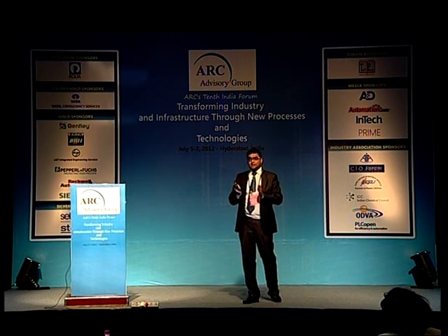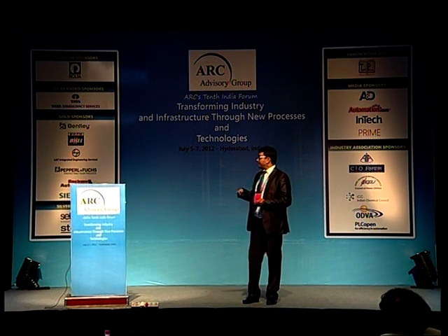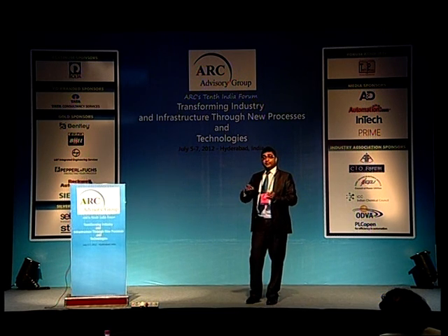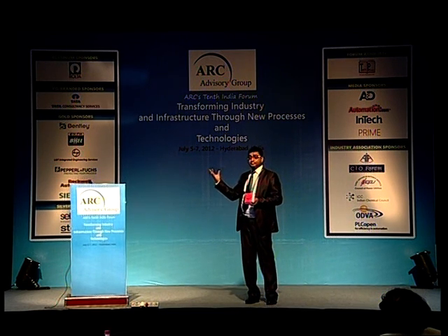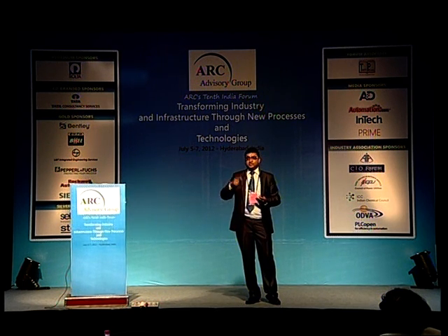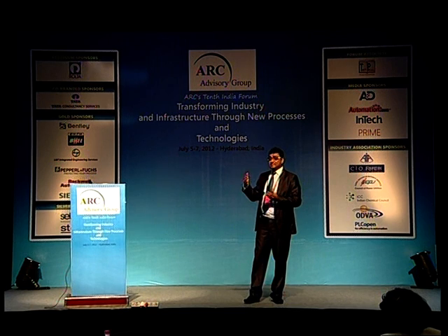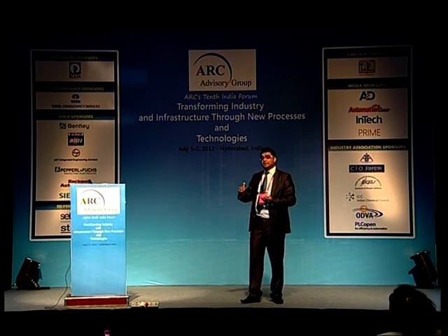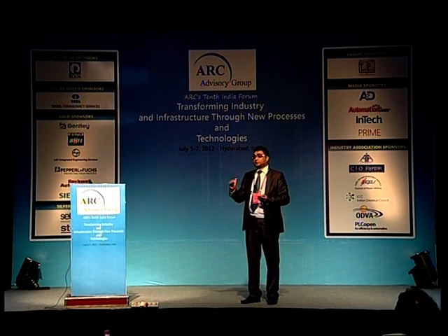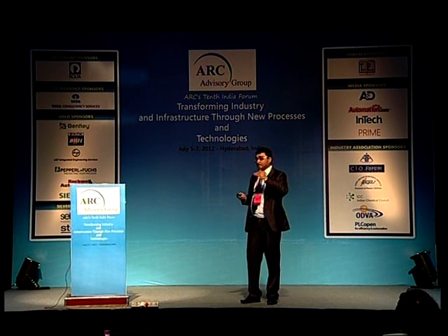That means especially for rotary equipment like fans and pumps, where there are vibrations or winding temperatures. For these particular systems, a lot of measurements are coming in as input data. So if you take the trend of this measurement data, it is very difficult to find out whether there is a sharp change in the value. So we need a sophisticated statistical methodology by which you can detect the sharp increase or decrease of the trend. This statistical process control identifies this change in the trend.